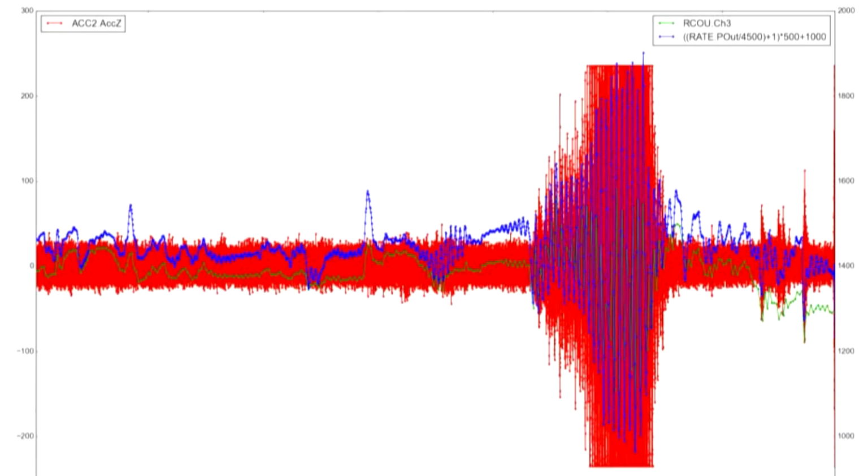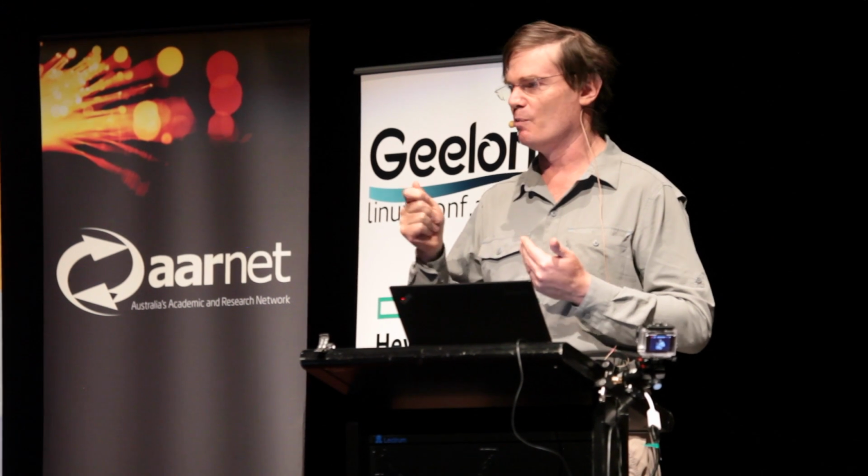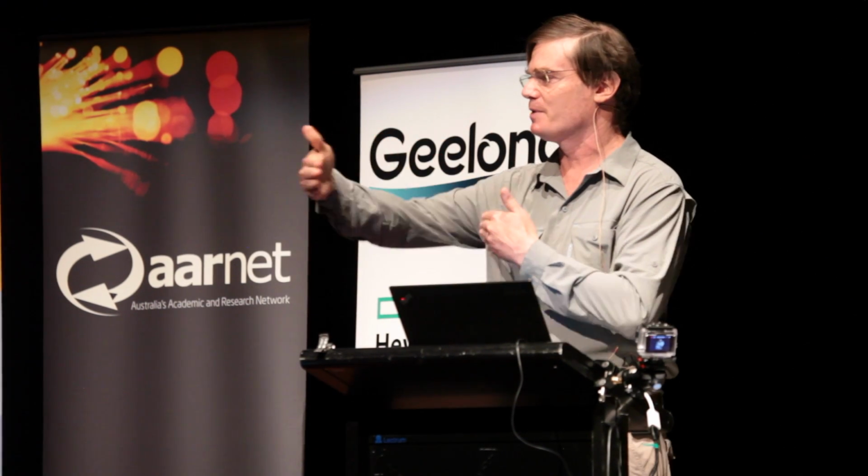And the pitch controller went out of control and started feeding back on itself, right? Because the oscillation is around the same frequency as our control frequencies. And so when it saw a movement this way, it pushed back the other way, and we ended up getting a build-up. And the whole helicopter just was shaking like mad.